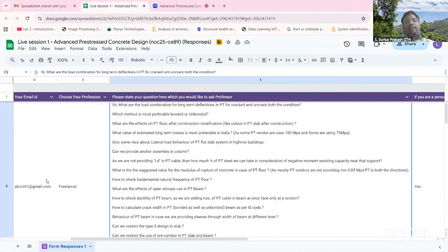The same way, in an unbonded system, maybe due to some untoward reasons, or due to carelessness by the working professionals, if they make some kind of a hole or do drilling, then they can accidentally damage an unbonded system. Then you lose all the beneficial effects of pre-stress. So it's just a culture. I think in Europe and India, we mostly use bonded systems. We grout it, and when you grout it, grout quality has to be really, really ensured.